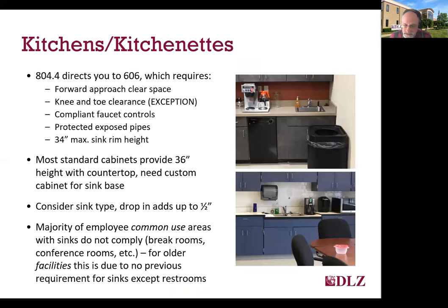804.4 addresses sinks and directs you to section 606 of the standards, which requires that sinks provide a clear space for the forward approach, knee and toe clearance, compliant faucet controls, and that the sink rim again is 34 inches high maximum, as we talked about in restroom sinks. So quite oftentimes in non-restroom areas, break rooms and kitchens and kitchenettes, we see sink rims that are 36 inches